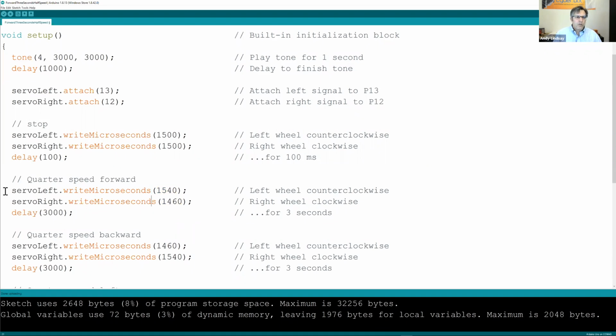Well, what we did to create continuous rotation servos is we took the same servo and just took the feedback mechanism out that lets it know where it turned to. And so what happens is when you send it this digital signal that it used to receive on an airplane from a radio demodulator, those 50 pulses per second digital signals, the servo doesn't have its feedback mechanism in there, so it never knows that it's reached 6 degrees counterclockwise of 90 degrees. So the motor keeps turning. And so that's the history behind that.